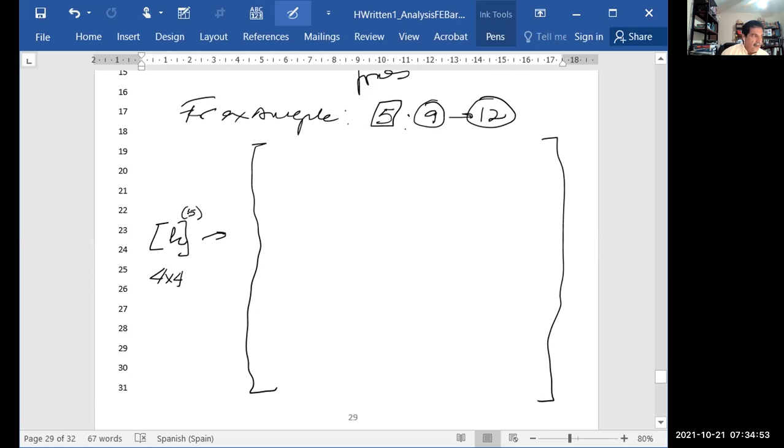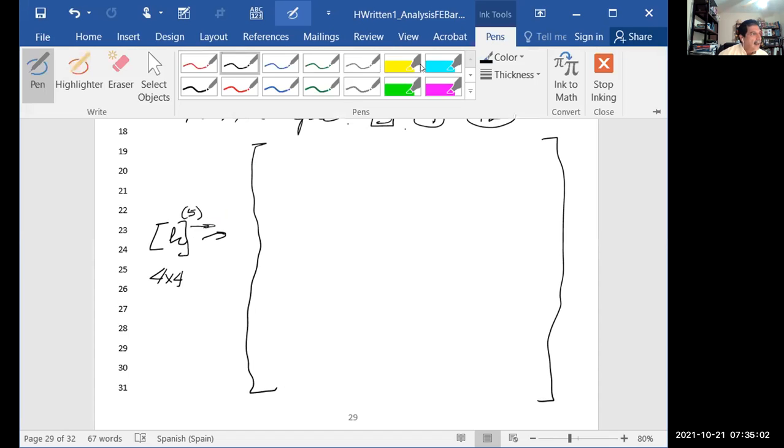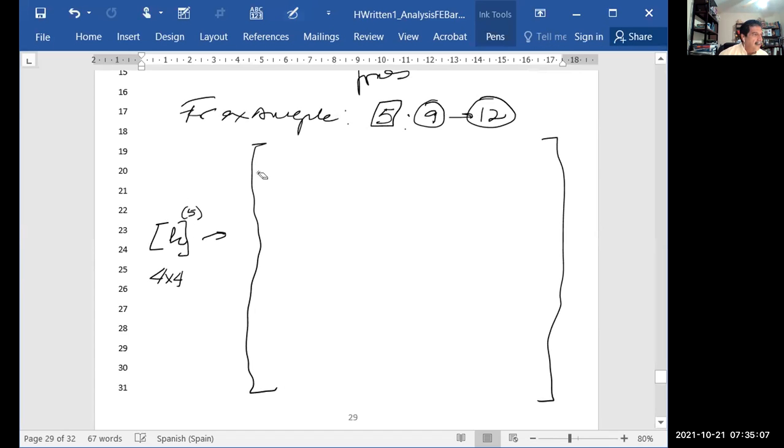Question for you. Let me change color just to help you. The first row of this equation, of this element matrix, the first one here, in what position, this is the big K, the global stiffness matrix, in what position is it going to be included?